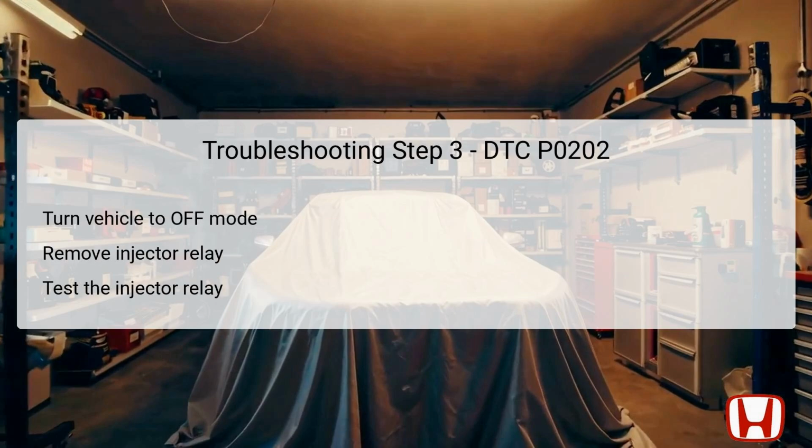For step 3, begin by turning the vehicle to the off lock mode to ensure safety when handling electrical components. Next, remove the injector relay from the under-hood fuse relay box. The injector relay is a crucial electronic component that controls the power to the fuel injector. With the relay removed, perform a thorough test to diagnose if the relay is functioning correctly.